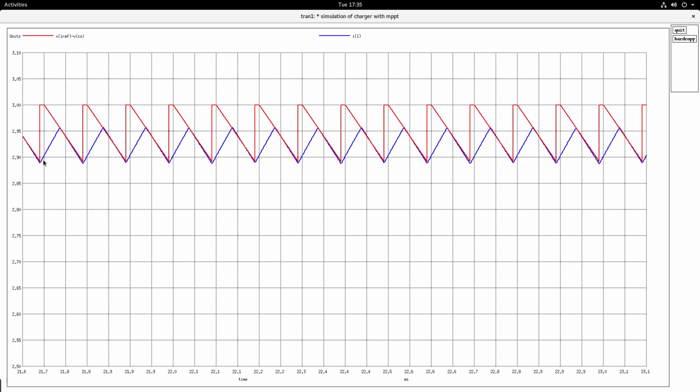And you see the inductor current, the moment it hits this at the down slope, the SR latch changes state, switches off that device, and then the inductor current is falling. So on, it keeps going. So this is also behaving exactly like what we anticipated, and you see that the inductor current is controlled to whatever value that you set.